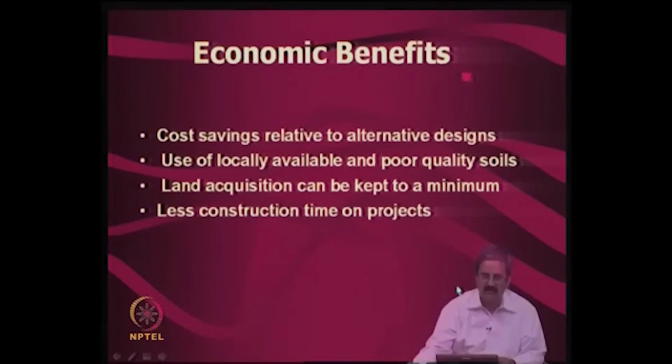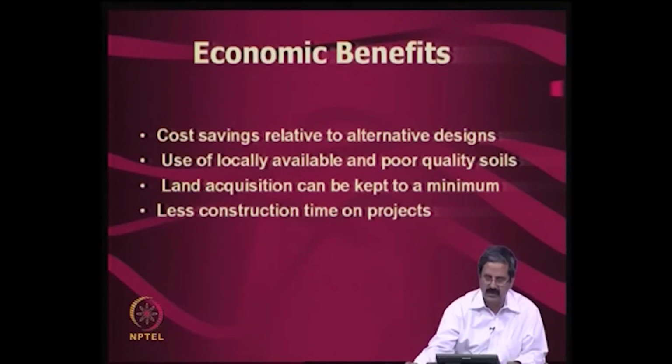Then of course, the economic benefits, like the cost savings compared to other alternatives. Time and again people have seen that these techniques are very effective and very economical. These will also enable the use of locally available materials and poor quality fills, as I just mentioned. Fly ash could be used, bottom ash could be used, any materials could be used, but one should do proper quality control tests and see that it is all right.